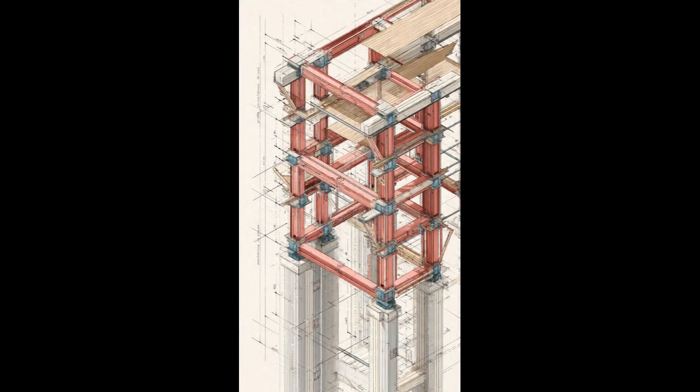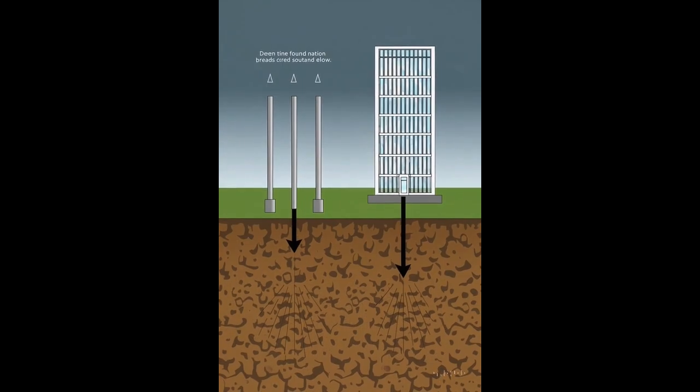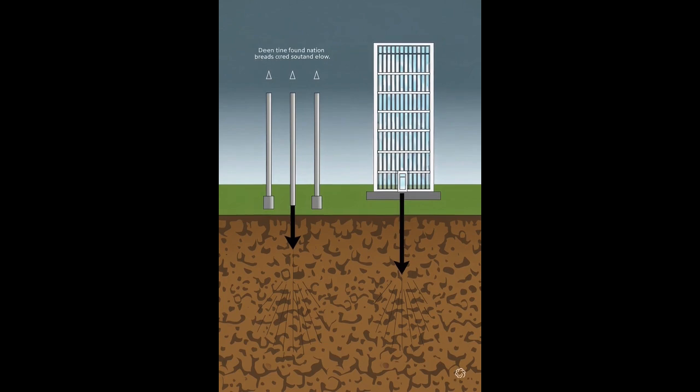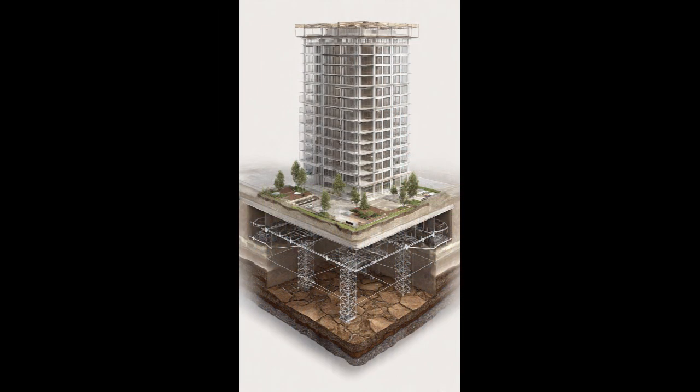Structural strategies, such as cores, brace frames, and tube systems, are used to manage lateral forces. Outrigger systems connect the core to perimeter columns, increasing stiffness. Foundations play a crucial role in tall building stability. Piles and raft foundations transfer loads deep into the ground where soil conditions are stable.